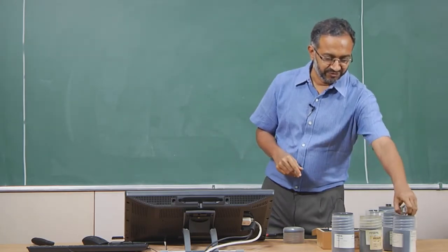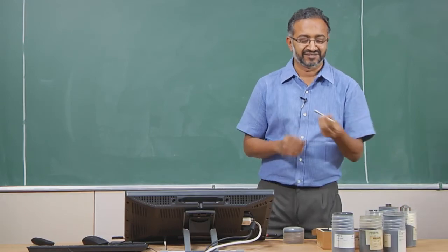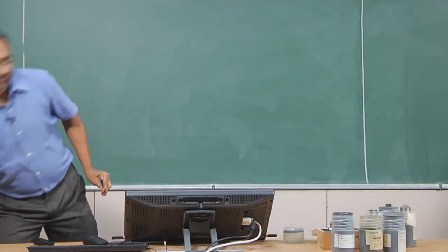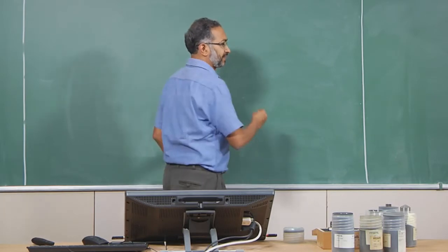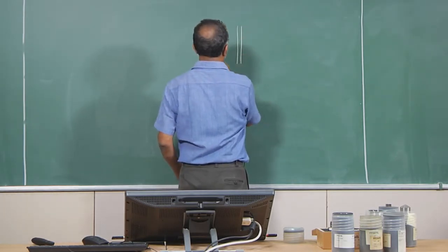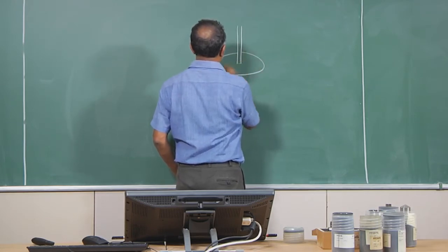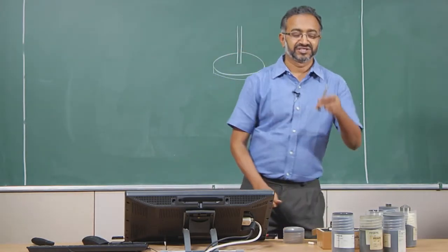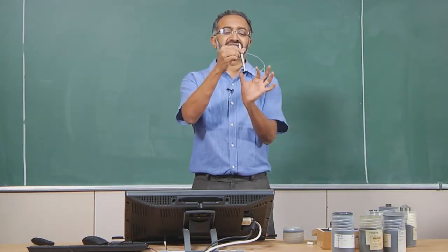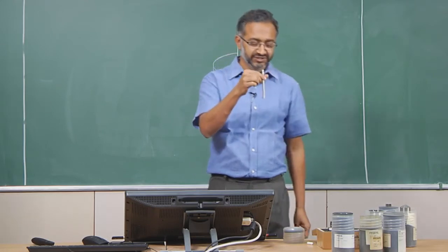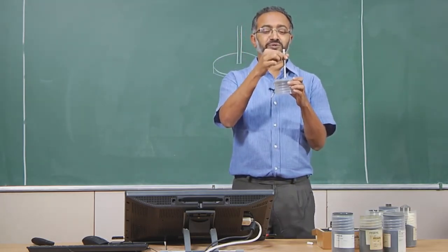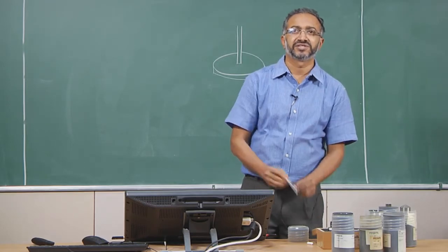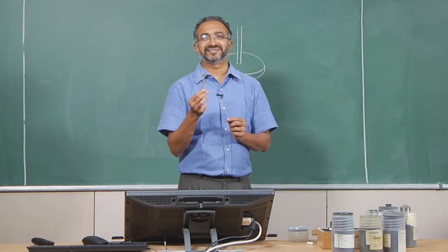If you see this, this is a parallel plate. This is what we've been drawing as a sketch. So this is the parallel plate basically. This is 25 mm diameter or 1 inch, and usually the other rheometer plate will also be there at the bottom. So we place the fluid here and then put the geometry and then start rotating. So this is what the overall parallel plate geometry is.